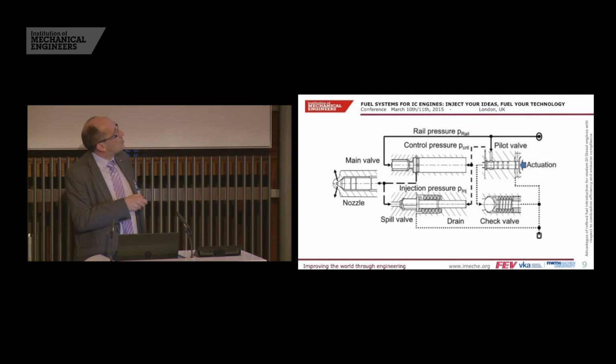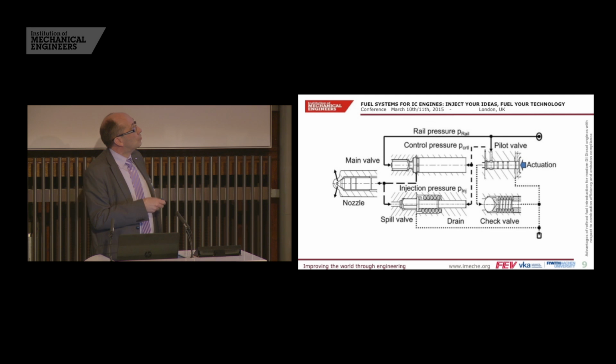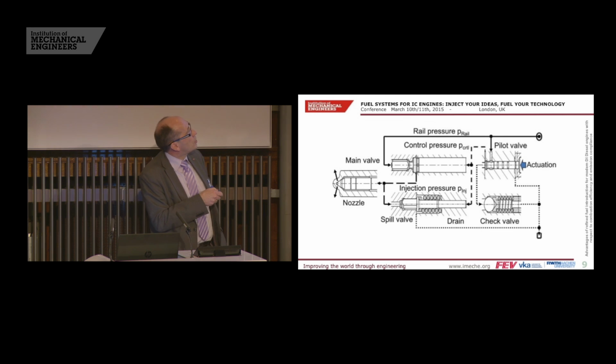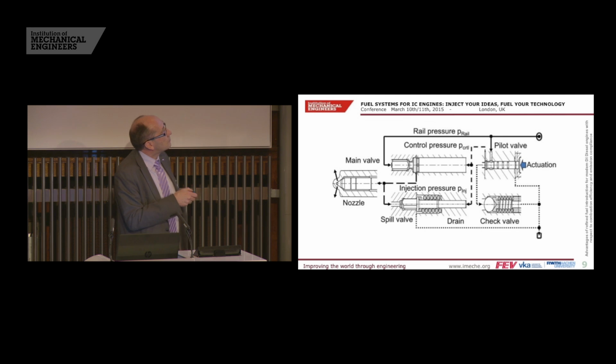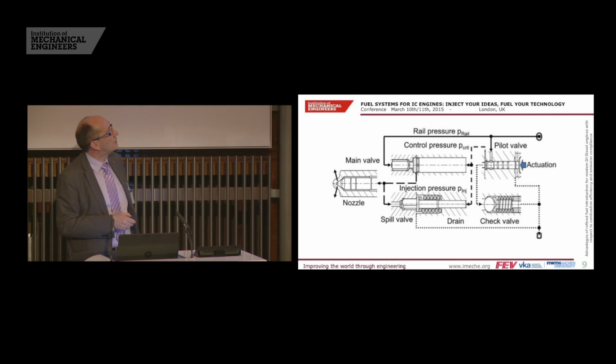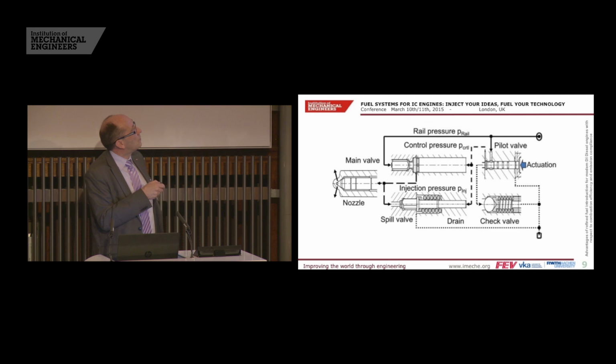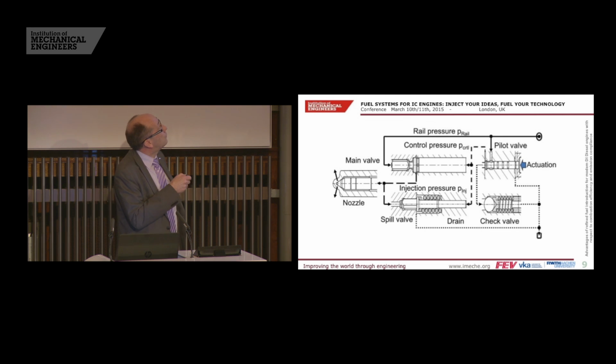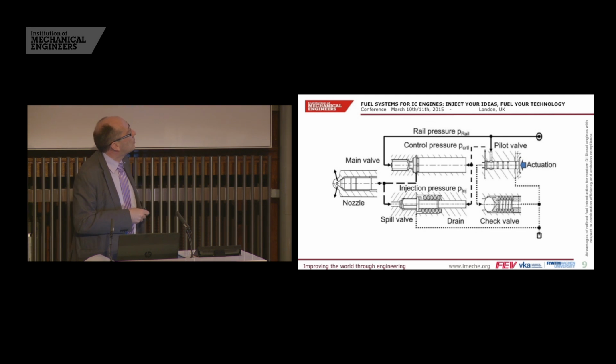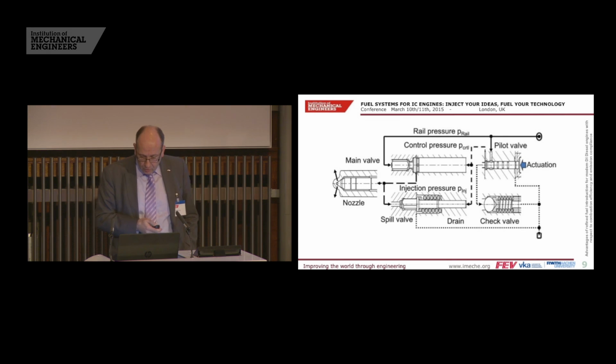And then we have the possibility with the piezo actuation to define the injection pressure, which is forwarded from the original source, from the rail. As I said, up to 2,500 bar, we can forward this directly, and it's used fully with the full momentum here at the nozzle tip in order to do the real fuel injection into the combustion chamber.